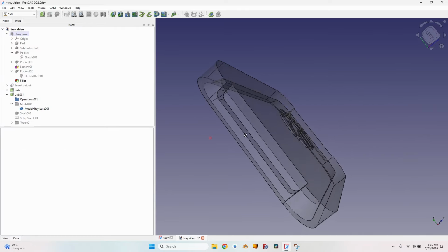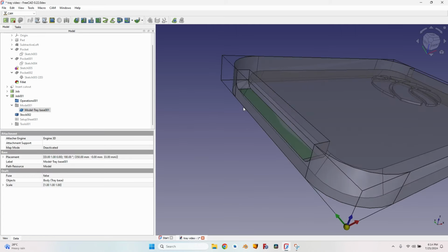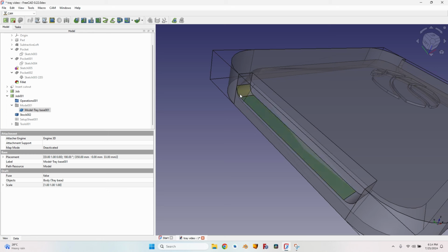The model that I have created has rounded corners. It looks very nice in the 3D view, but I will have some issues selecting the surfaces for the 3D operation. Here is that part when you simply end up hating FreeCAD, because you cannot mill these rounded pieces. It will result in an error in the normal pocket operation.